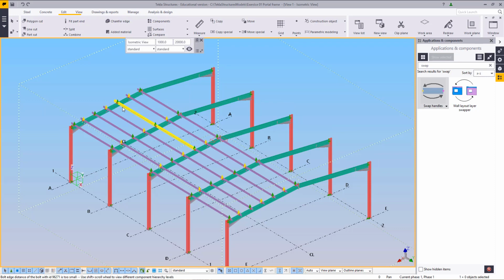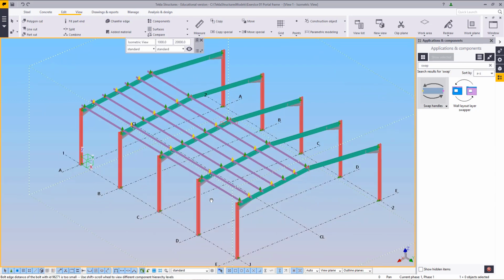Right, now once this is done, let's put in some bracings. A portal frame like this will always have a set of bracings on at least one of its bays, and these wind bracings and stabilization bracings are basically, firstly, stabilizing the thing during construction, and secondly, if strong wind blows, keeping the whole thing from toppling over.